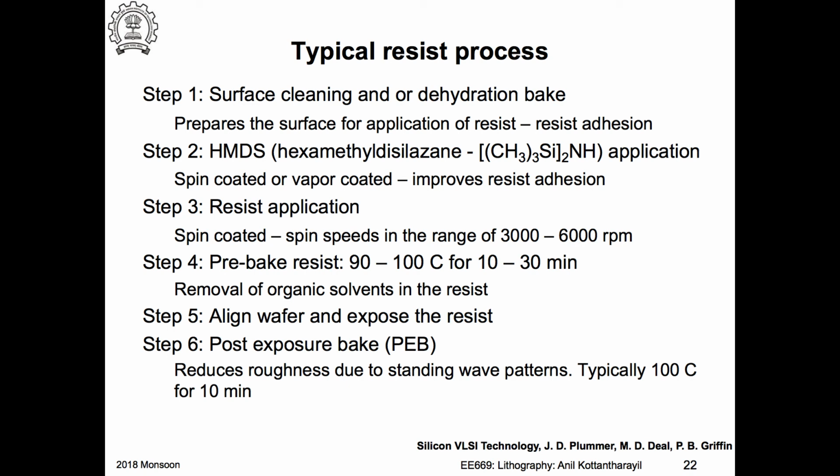Very important thing for photoresist is that this is a photosensitive material. So you can see the bottles of photoresist. They are actually glass bottles, nearly opaque, so you don't want any light to get in. They're sensitive to moisture. Photoresists usually come with a shelf life, typically in the range of 6 months to 1 year.